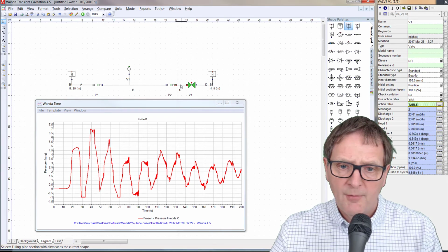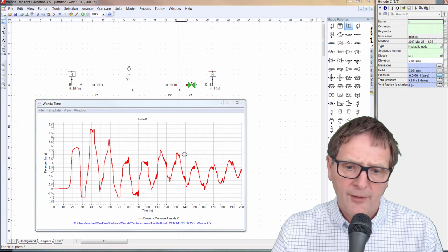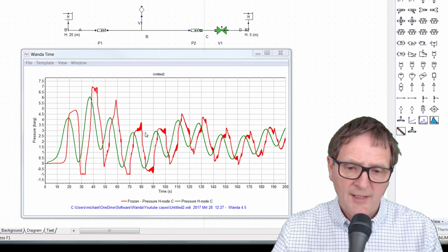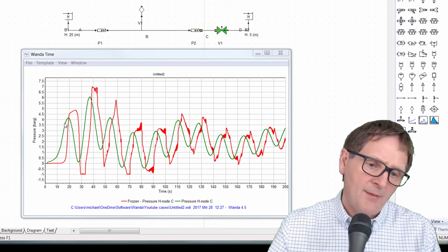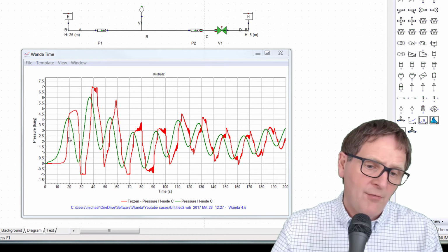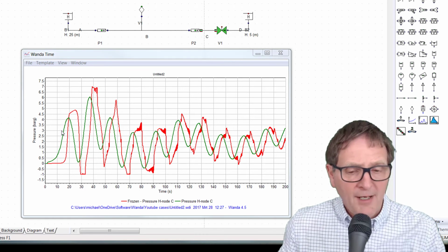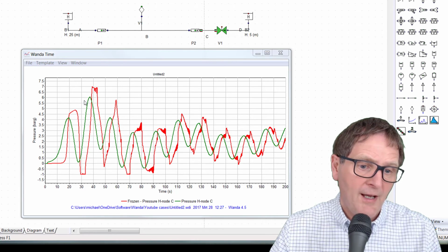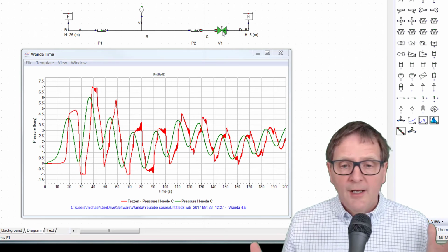So if I now go back to this point here and I take those pressures and put them onto that graph, you can see it's obviously gone down, and the pressure's starting to rise a bit earlier because it's actually doing something useful at the start now. Because the closure is over a longer period of time, the actual effective closure is over a longer period of time, and the surge pressures that rise have been reduced.